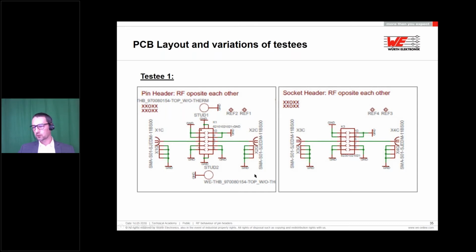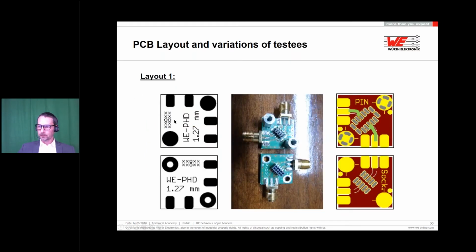And this is also the reason why we suggested 2 different layouts. If it were just about the insertion loss and matching, then okay, we could just measure the different pin combinations, that's it. But for the crosstalk, we need to measure 2 lines at the same time. That's the keying of the components, so that we can see quickly when we have it in hand, oh yeah, those are the 2 pins we are using for the signal.